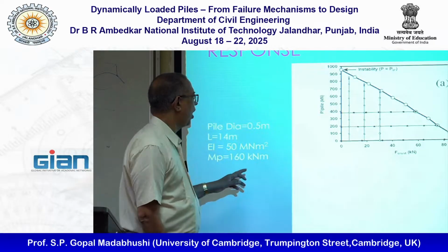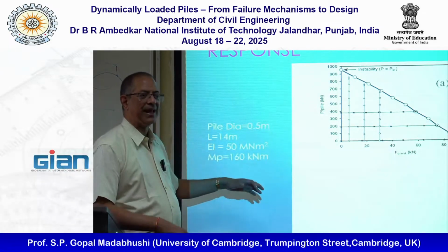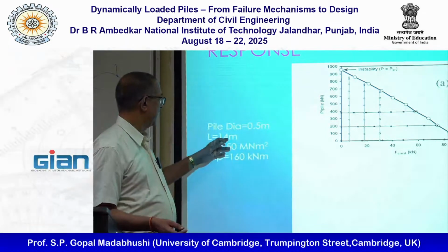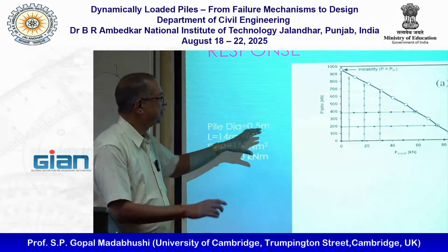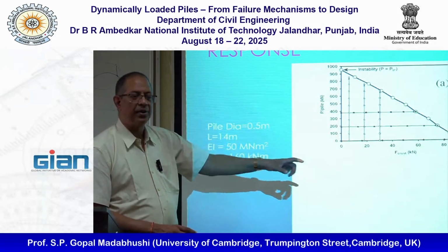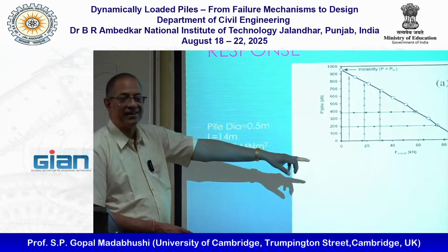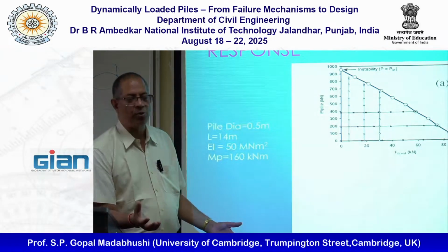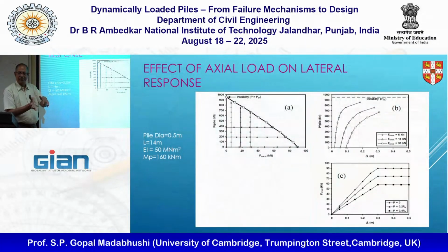Now you can say, how will all this change if you've done this for 0.6 meters or 0.8 meter or 1 meter diameter pipe? What happens if L changes and so on? Yes, this gives you a starting point, right? So then you can say, well, I got a longer pile, then obviously my P crit will become more critical. That's common sense, right? I got a stiffer clay crust, the force F crust will go up. So you can at least as a first point for design do that.